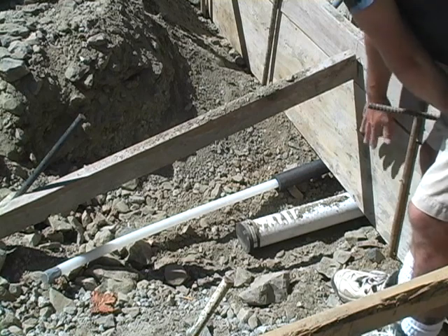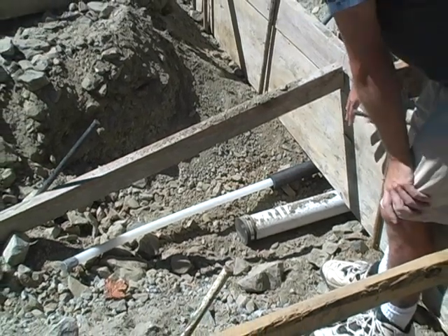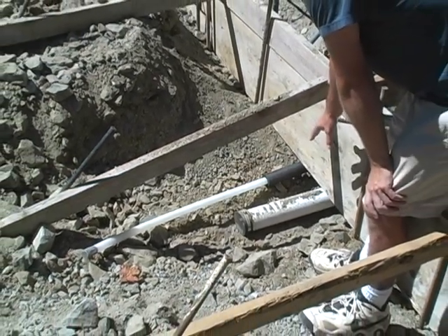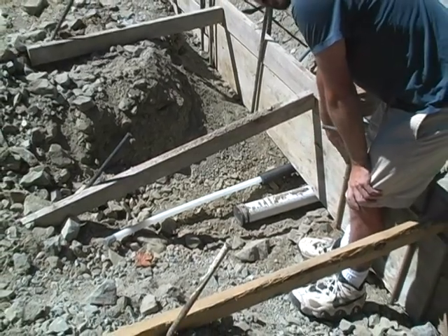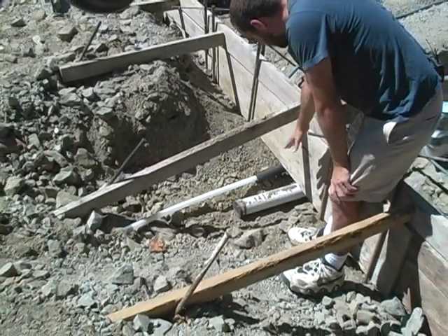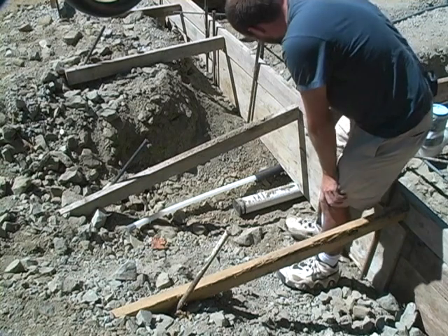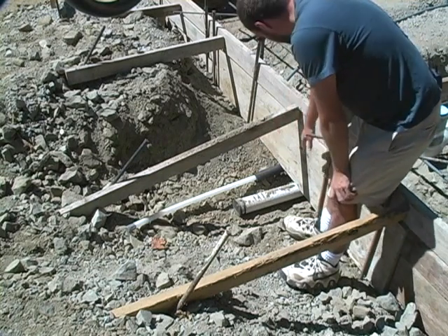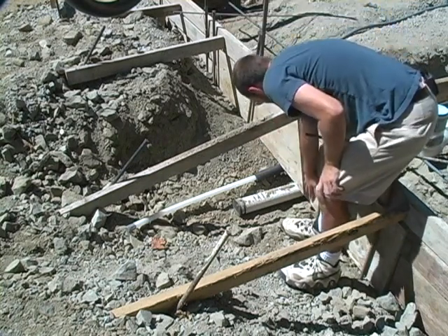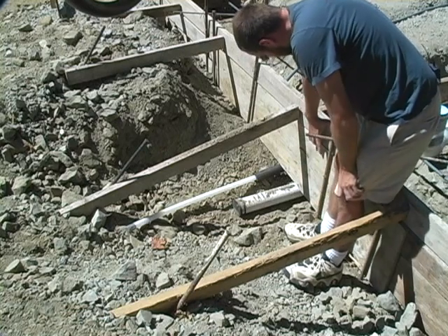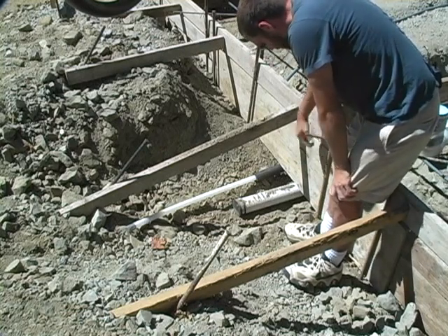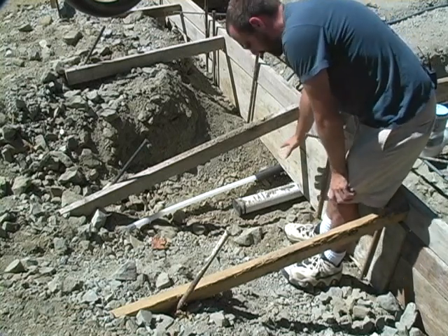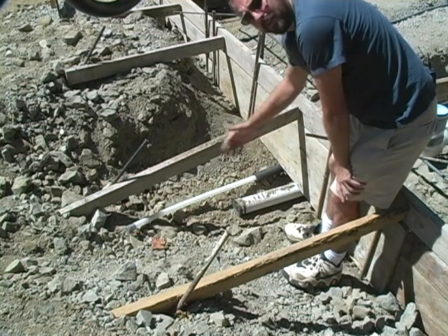And you can see in this end of the building, we have a very deep footer. We had a lot of fill that we didn't quite trust the structural strength of, so we dug down through it until we got to natural grade. This is a pre-existing fill. So what we've done is use a large form board on the bottom and then continue up with another 2x6 on top to get the height that we needed to be able to fill all of this in with concrete without it flowing out from underneath.